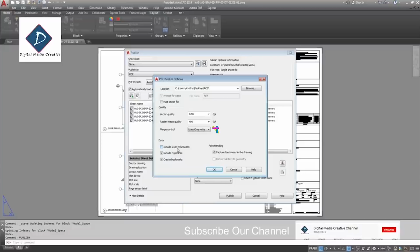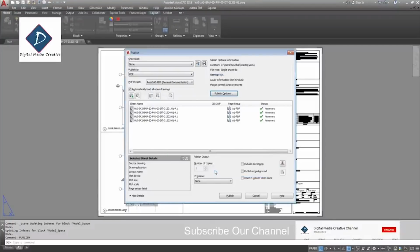So the thing is, whenever we export the PDF, you can see in the properties bar all the layer information. You can click turn off or turn on, you can control it. But normally whenever you send it to a client or someone, make sure you are not including this one. That's a standard. Okay, then I'm just clicking close.